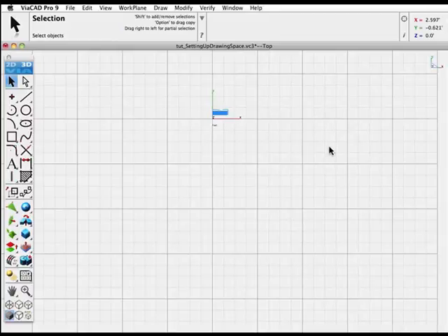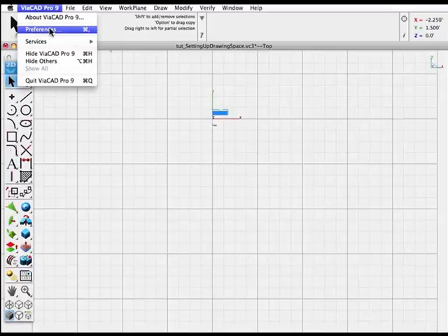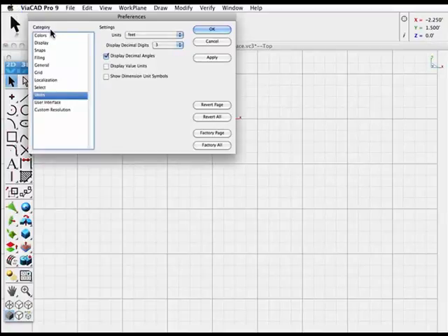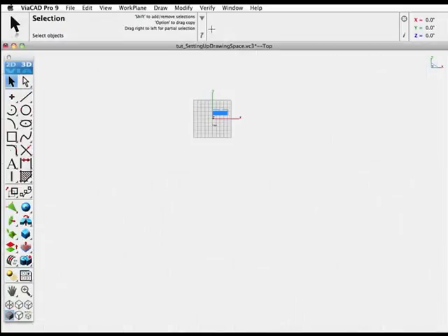Back to our units, and you can switch between dots as subdivisions or grid lines. If we change to feet, inch, fractions, the unit of measurement also allows you to set the precision. This will affect any place a length, size, or dimension is displayed.